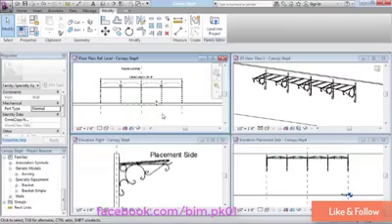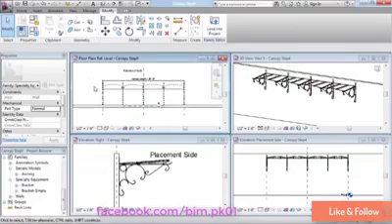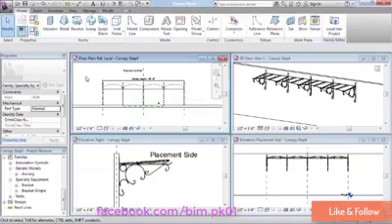to start behaving again. Now, I want to add one last finishing touch to this before we complete it, and that is a flip control. This is sort of an optional feature, but it's a nice feature. If you remember that when you add doors and windows, they have those little double arrow flip controls. It makes it real easy to reverse the direction of the door.